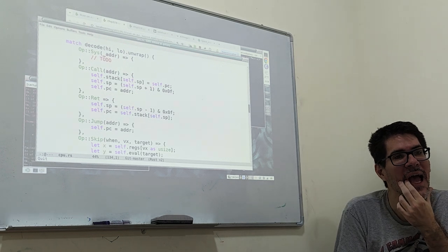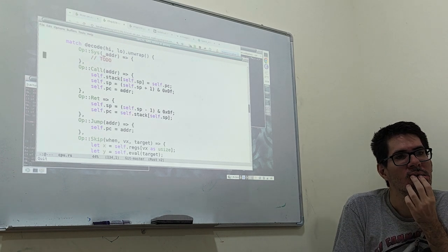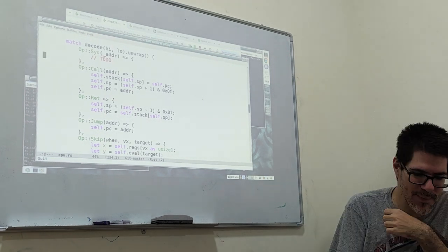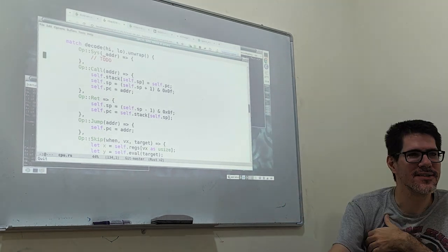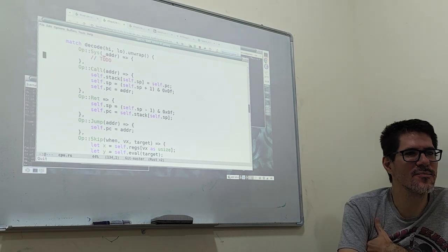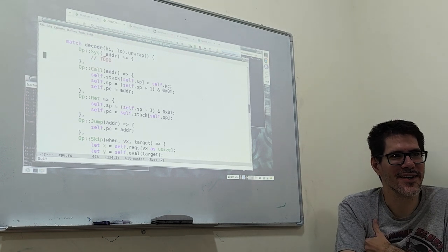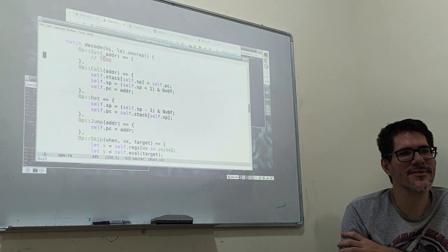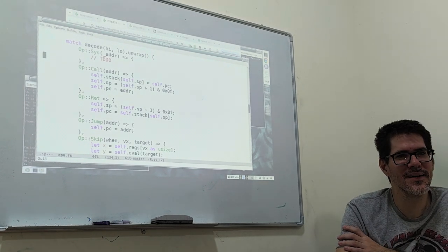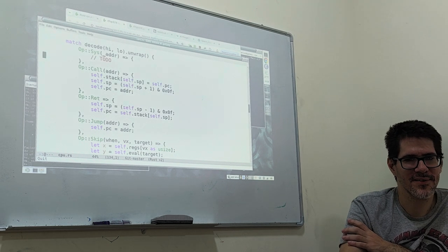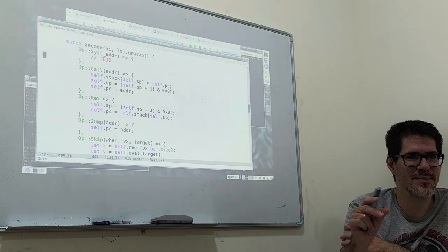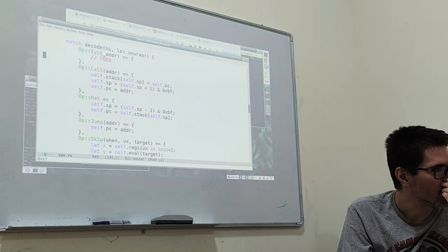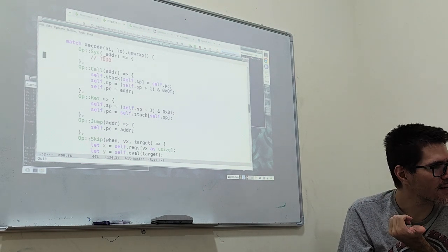So yeah. You said earlier that the no STD and the match didn't work. No, not because of no STD. Nothing worked. Match was one of the high-level constructs that didn't work because it was just complex enough to not work. What I mean by that is that the LLVM AVR backend just barely worked to have literally the simplest possible program, just blinking an LED. So it would be a compiler error because match translation was not supported, if you were lucky, then yes.